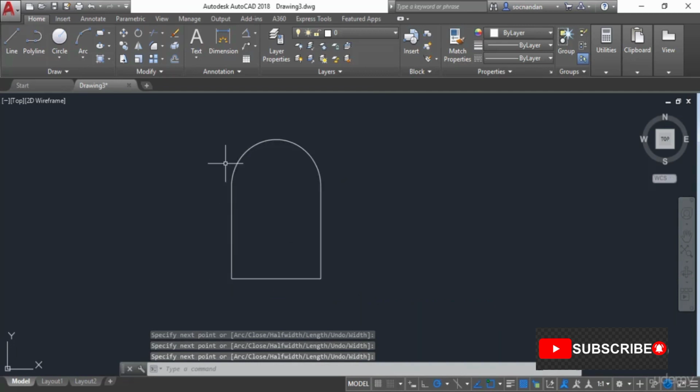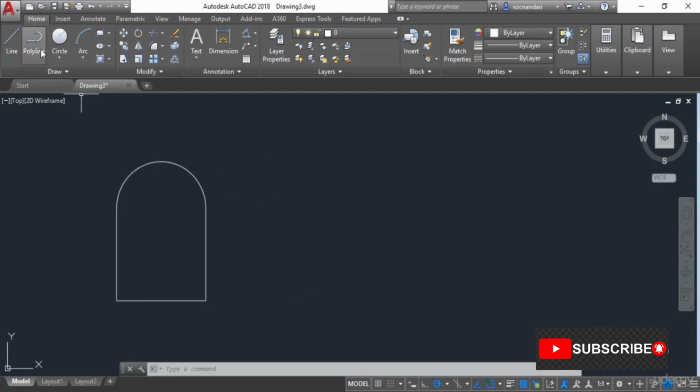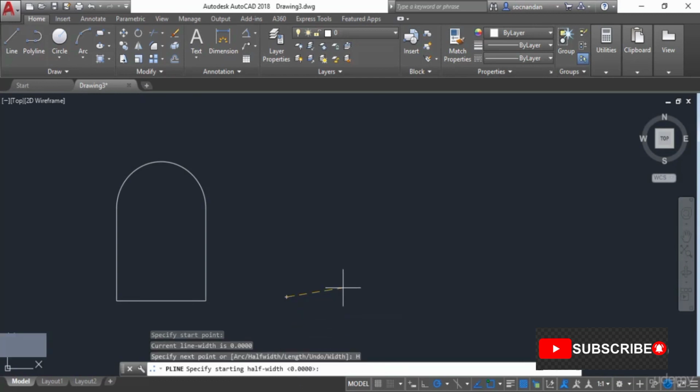So using a single command, we can make this kind of geometry which has this little line segment, and also the arc shape. And the polyline tool can be used to make it. So now let's select this polyline tool and let's look at other options related to the polyline. Now I'll click at a point and now look at the command line. Here we have this option of half width. Let's select it. And now let's apply a starting half width of 10 units and press enter.